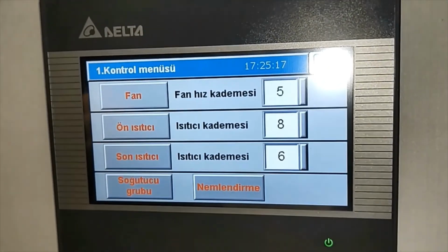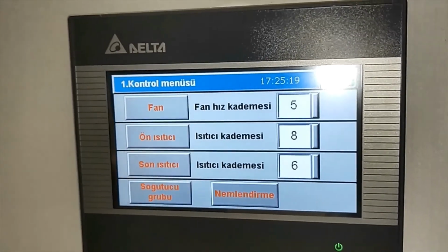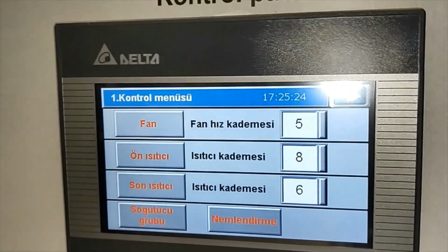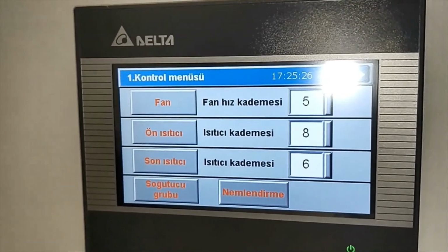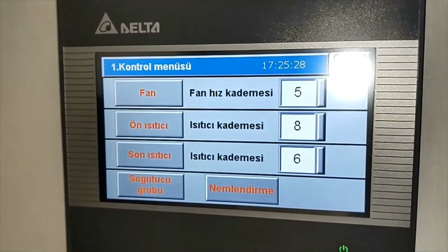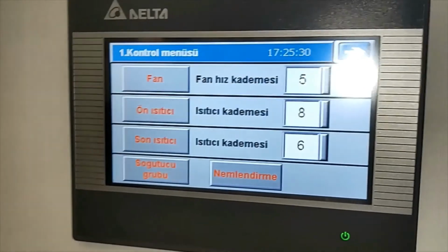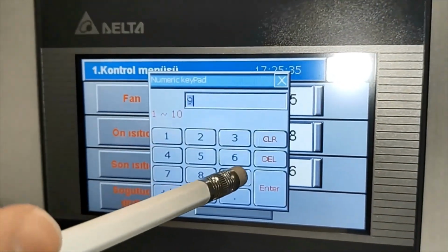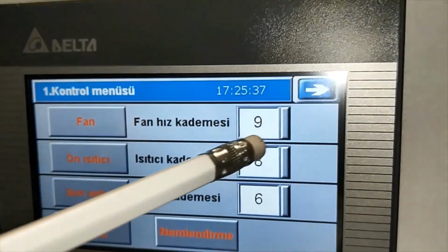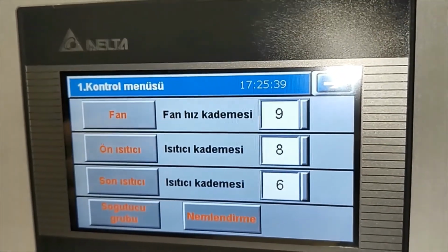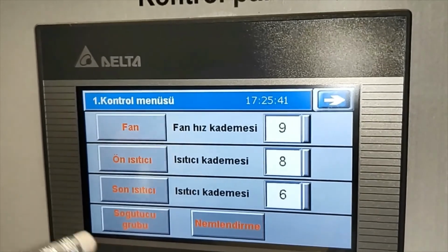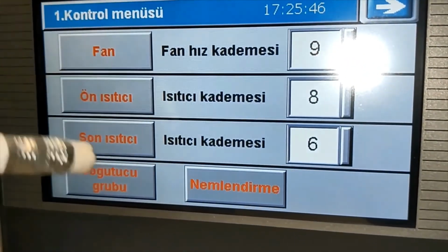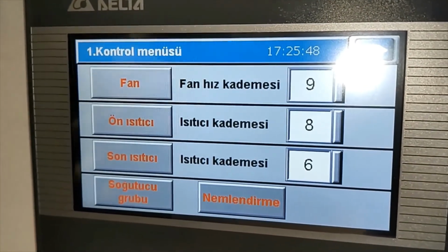In this experiment, two seasons can be observed: summer season and winter season. Let's start with summer season. For summer season, radial fan, cooler and afterheater should be switched on. Cooler one should be levelized to the higher level, because we want to cool air. We want cool air.